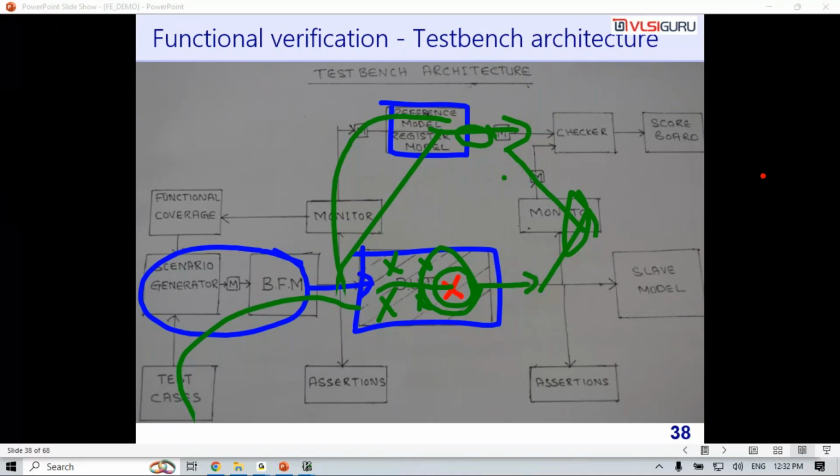Yeah, please ask. But actually, in verification, how can a verification designer make a reference model? Because I also have the design specification. Whatever document the design engineer has, I also have the same document. He will read through the document and develop the DUT, the design. I will read the same document, understand it myself, and develop my own code called the reference model.